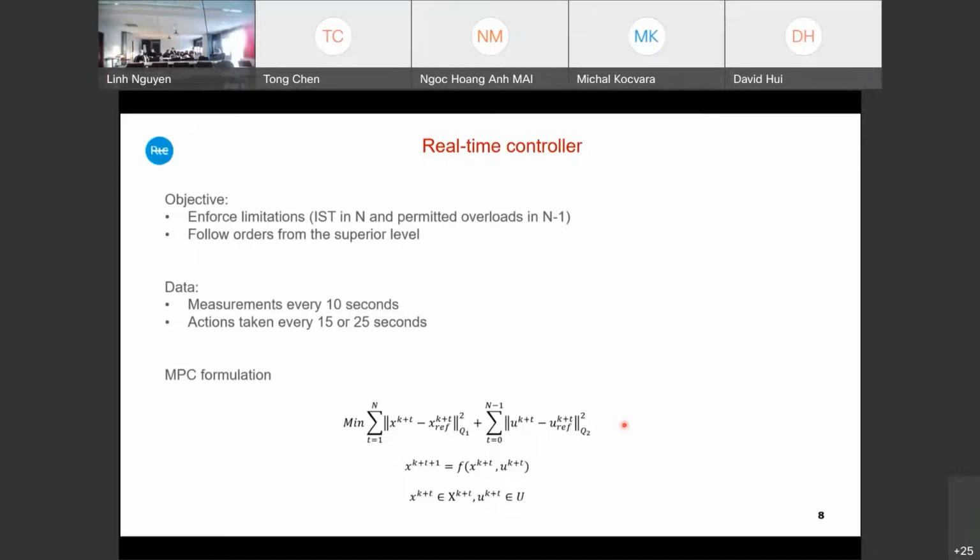And the idea of model predictive control is that, first of all, you have a model. So we have embedded in these equations some model of the power flow equations. The model predicts the behavior, or gives a prediction of the effect of the controls that we will take. We don't really have any forecast in it.